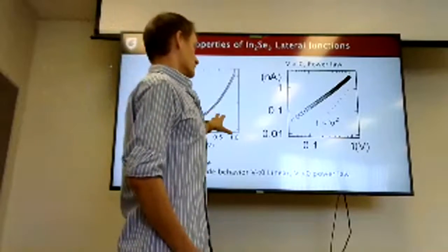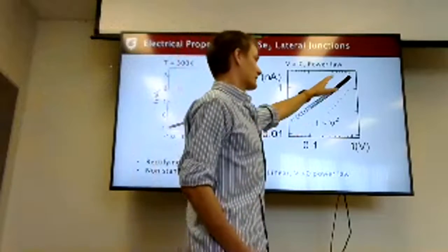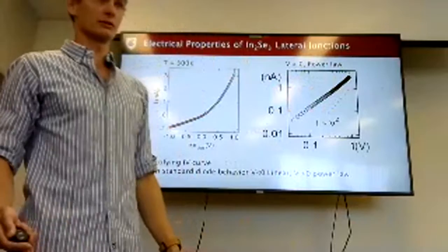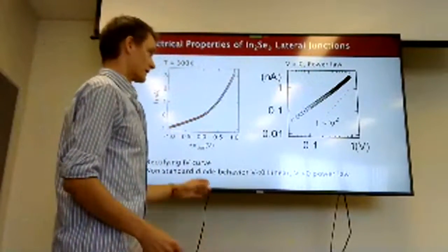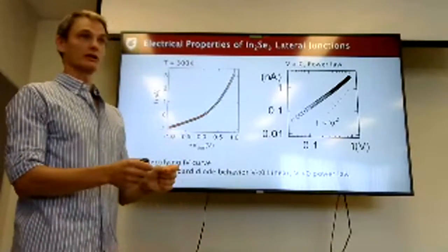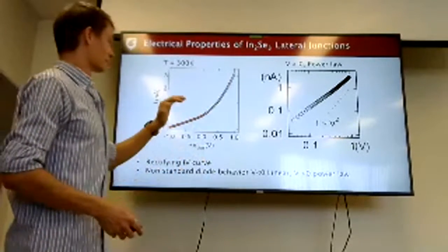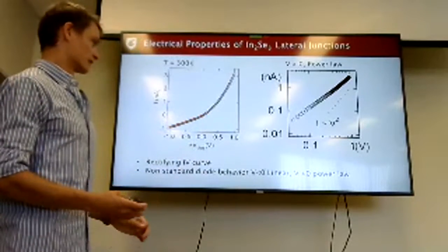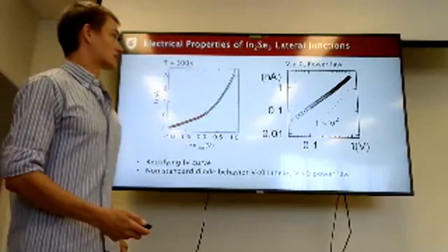So the first thing we do is make a semi-log plot of the positive voltage. And what we see here is a straight line. This straight line is very indicative of space charge limited current transfer. So, all right, we think maybe we're not wrong there. And then under negative bias, a dipole can't completely screen the external potential, whereas a parallel plate capacitor would. So we think maybe there's something going on there. So we get a rectifying IV curve, but it's a weird rectifying IV curve that we need to think about and explain. So we do some simulation work.